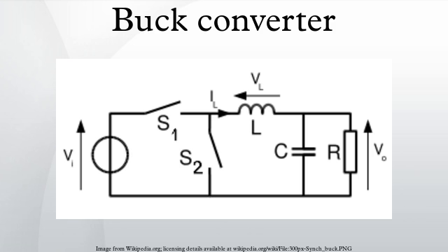Continuous mode. A buck converter operates in continuous mode if the current through the inductor never falls to zero during the commutation cycle. In this mode, the operating principle is described by the plots in Figure 4. When the switch pictured above is closed, the voltage across the inductor is V_L = V_i - V_o. The current through the inductor rises linearly. As the diode is reverse biased by the voltage source V, no current flows through it.